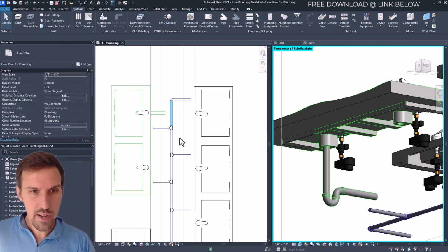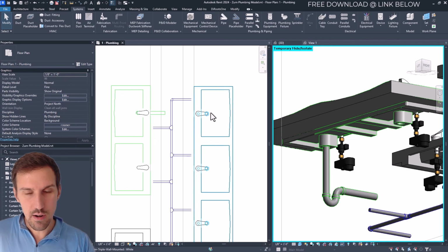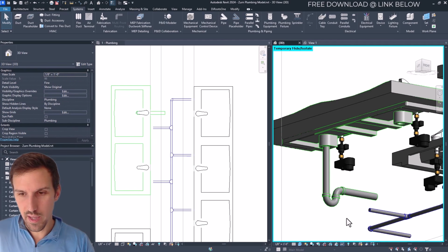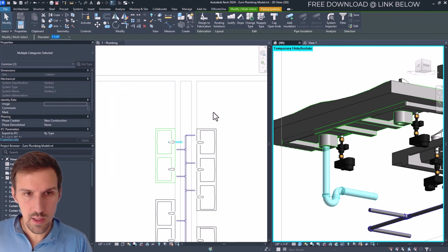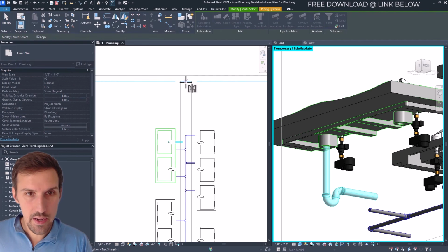So this is looking great. Now, a lot of times when I see that I've done something that I can mirror, I will do it. So I'm going to go ahead and select everything that I want to mirror over. Right here, we've selected it. Now let's click into the floor plan right here. And we're going to go up to the mirror draw axis and I'm going to click on it. And I want to be able to mirror it from the midpoint of this chase wall, but I can't snap to anything, unfortunately. So I have to do something different.